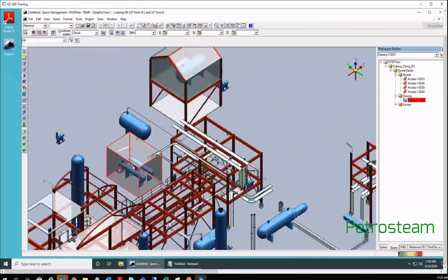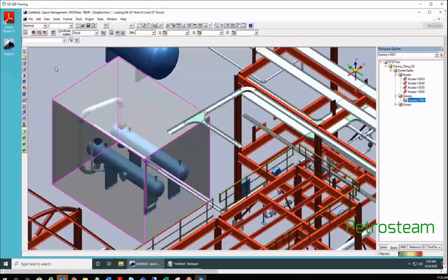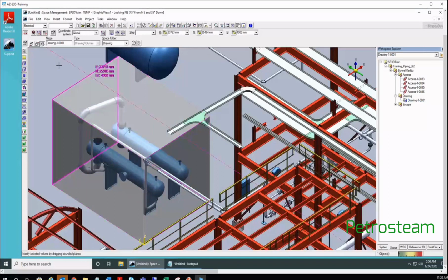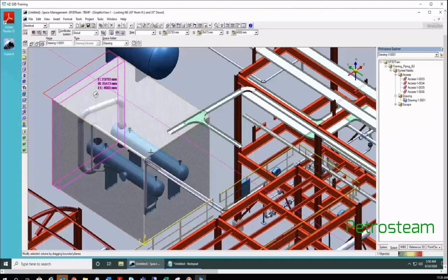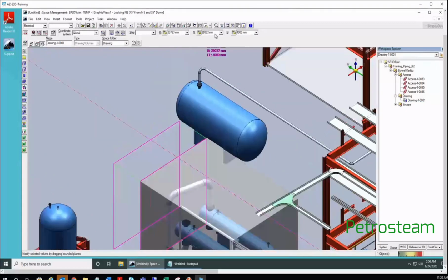Okay, so select again. You can go for handles option. If you select top, so sorry, it has selected the north face. So north face now, you can select anywhere you want. You can key in also value if you want to modify. These are all absolute coordinates, as per global.